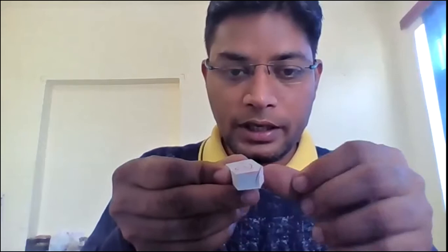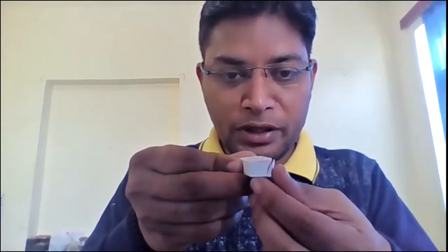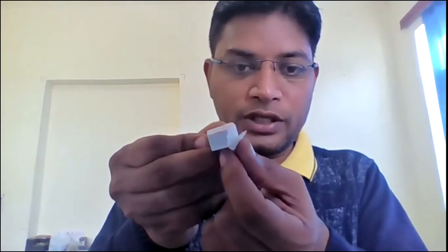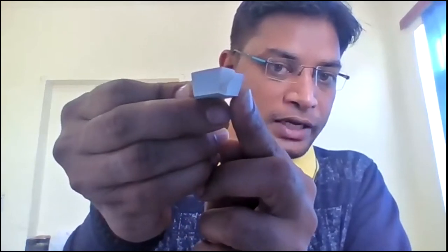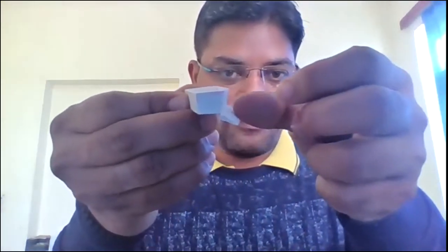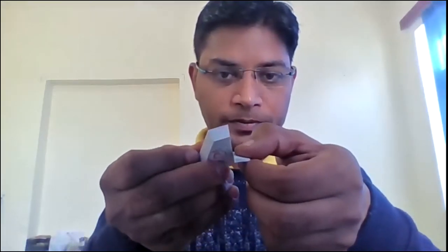Okay, can you see that I'm keeping this as the top portion, and I remove from the side. Initially at the top there is a very small thickness, at the bottom it is this thick, the thickness of the material removed is increasing. So this surface will look like that. Okay, I'm removing this amount of material. This is done. Now similarly I am keeping this tool over here, and when I removed this material I planned like this, but now I'm keeping it at some angle to create the edge.